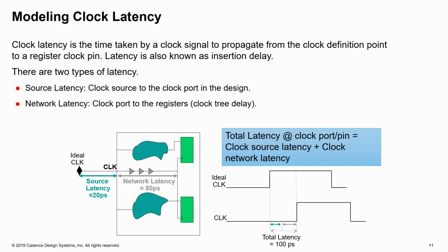Any buffering that you do inside of your design is known as the network latency. So these latencies are modeling the effect of the clock before and after it comes into the design, and what happens to it through the buffers and so on.